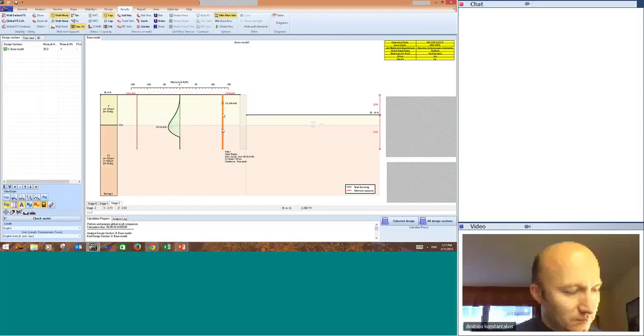This red line is the design capacity of the wall. So one of the things that we see is that we have optimized the length, because if we click on wall embedment safety factor, our wall embedment safety factor is 1.537. We're not really so much optimized for the bending moment. So this looks like it's over-conservative.